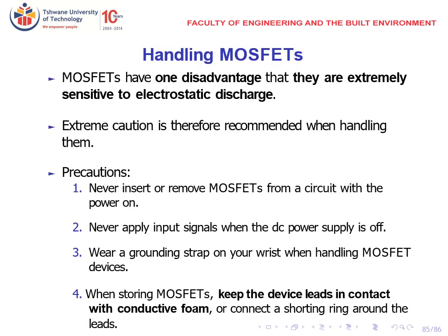Handling of MOSFETs. MOSFETs have one disadvantage: they are extremely sensitive to electrostatic discharge. Extreme caution is therefore recommended when handling them. Precautions: never insert or remove a MOSFET from a circuit with the power on.